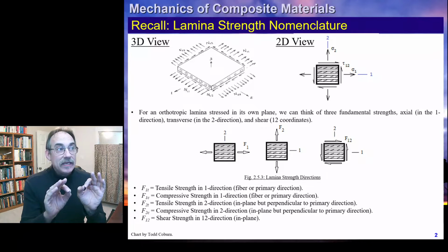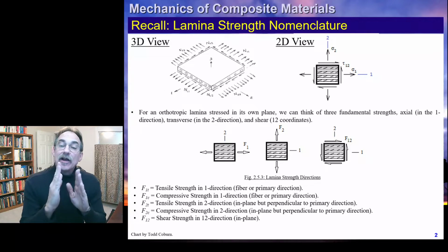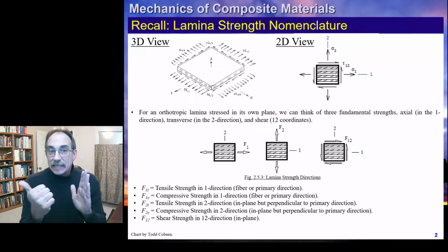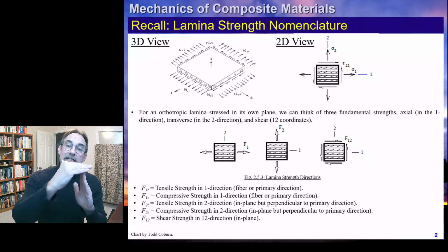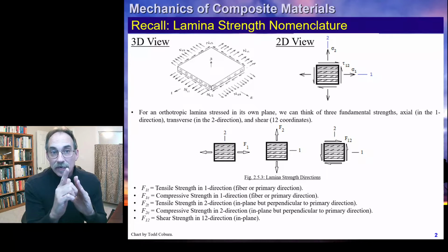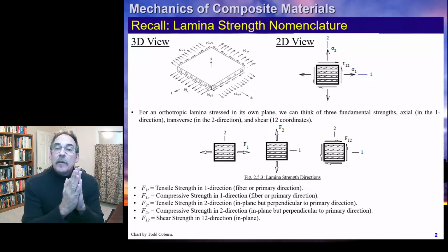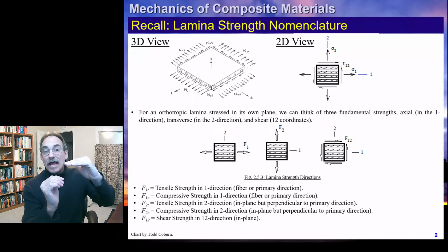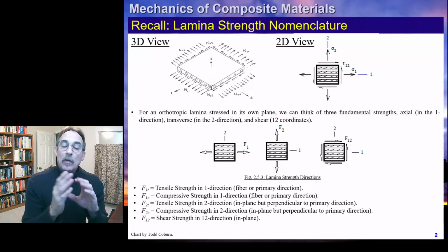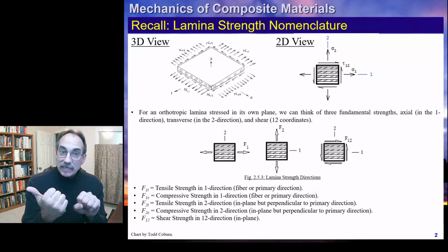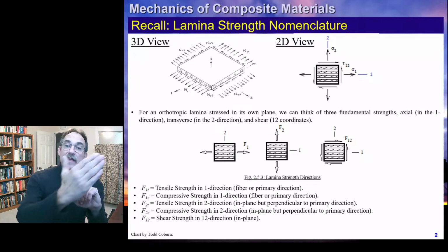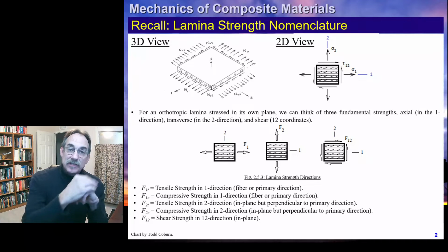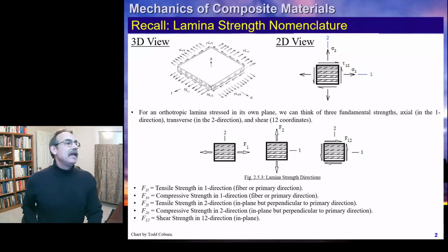Positive sign convention means the stress acting on the positive x face is acting in a positive direction, and on a positive y face is acting in a positive direction. And for shear stress, positive x face in a positive y direction, positive y face in a positive x direction. And the converse on the other side: when we go to the negative x face in the negative direction, that's also positive, and so on.